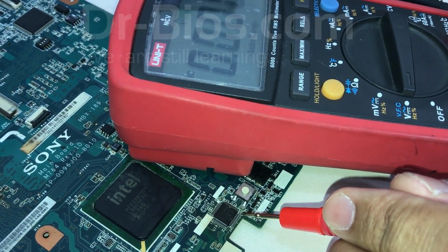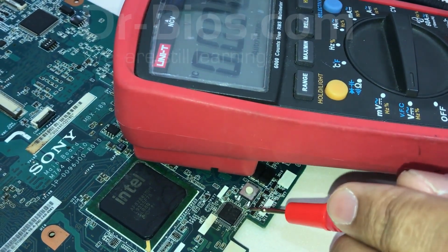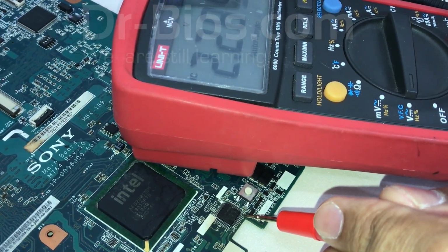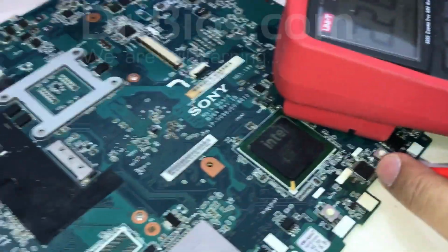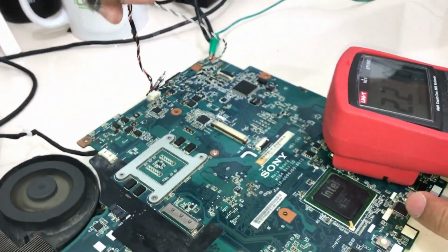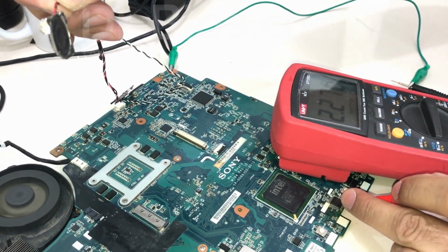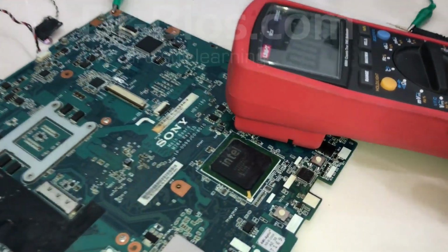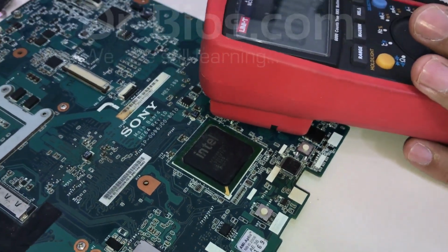If voltage is absent in here, then you can check power, which I did, but I didn't mention it in the video. Now I check it again. 2.2 volt. There is noisy sound. By placing my finger on the probe, the noise will be applied from my hand and is transferred to the speaker through the amplifier. Let's assemble the laptop and check the audio.